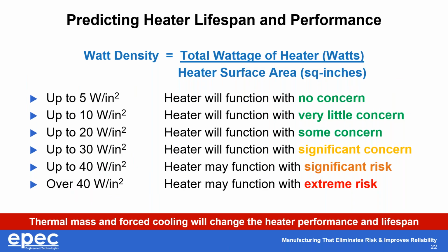We typically want our heaters to function for the life of the application. That's years for us. For some of these, especially the ones that are 40 watts per square inch or higher, we can build it and it'll turn on. But if it's not attached to a sufficient thermal mass, the ability to draw heat away from the heater itself, it may only last 100 hours or 10 hours. And for some of our customers who are involved in test engineering or destructive tests, they don't care. Maybe their test is only 10 or 20 minutes. So as long as it lasts longer than an hour, they're happy with their design and our solution.